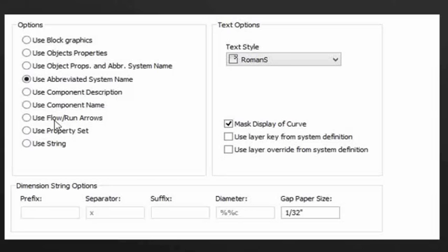The flow, runs, and arrows will allow you to use just a graphic for your arrow, and that's useful for showing direction of flow. It's also associated with the direction of flow of the pipe. So if you didn't realize it, you are able to set the direction of flow on your pipe if you want using AutoCAD MEP tools, and your flow arrows will pick up on that and automatically switch to the direction that the flow is set to on the pipe.